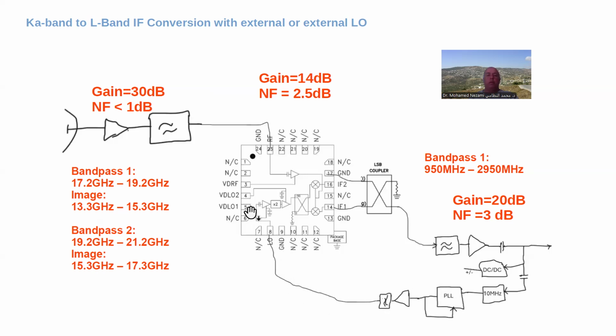And so I come in here, and internally it has a DC block. Of course, there are DC blocks on all the ports except the IF. The IF is DC coupled so that you can have a direct conversion receiver if you want out of this. So I come in here, double the frequency, amplify again, and then of course you go into a quadrature 90-degree hybrid, which is internally terminated on the oscillator part.